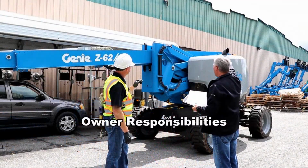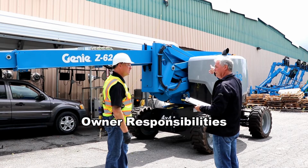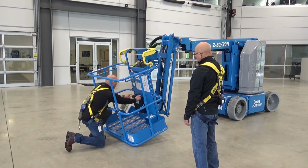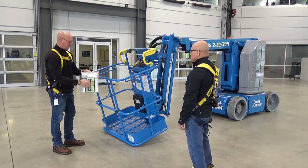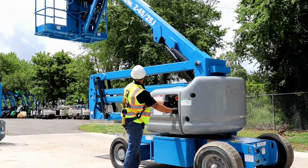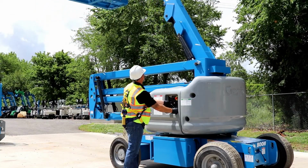The owner of a Mewp could be the dealer in a rental situation, or may have the responsibility of a user if they are directing operators to operate a mobile elevating work platform. It is the owner's responsibility to make sure that the manufacturer's operators and any other safety manuals are in good condition and stored on the machine. And just like a dealer, the owner must properly maintain the machine to the manufacturer's specifications. The owner should always ensure that any personnel that they direct or authorize to use a Mewp have received appropriate training and familiarization.